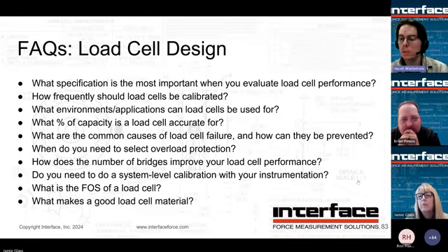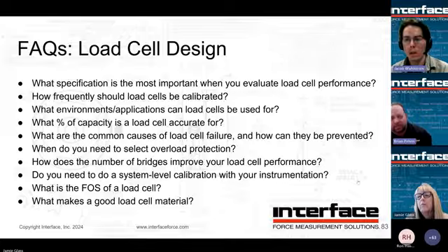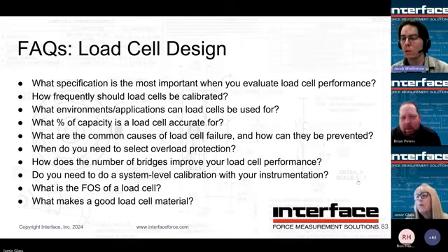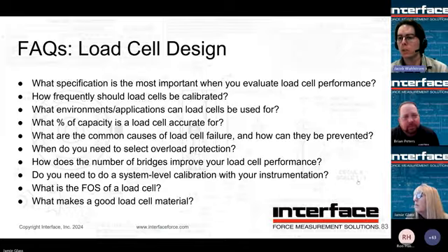Yes. I also would like to point out, is it from 0C to 170C, or is it a 170C spread? Because if it's an aluminum load cell, it could be going above the rated operating range. Basically the aluminum could be tempering and the material properties changing there. Or gauges separating from the flexure.